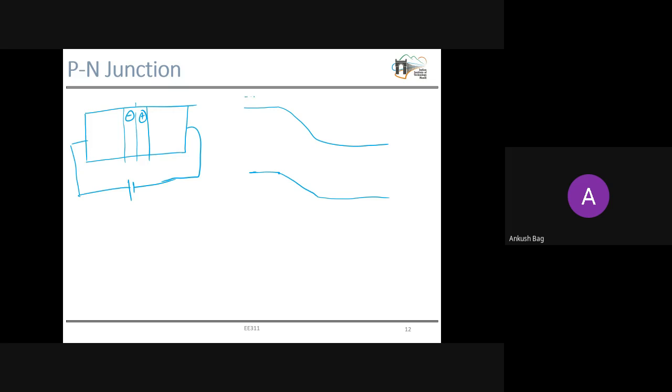Let's say earlier we had this conduction band here and valence band here, and due to the application of forward bias VD, this built-in potential is reduced to here. Earlier this was the potential barrier. Now due to the application of forward bias qVD, this is reduced to here. The potential barrier decreases. Now in terms of carrier distribution, what is happening? That is important to understand the current.